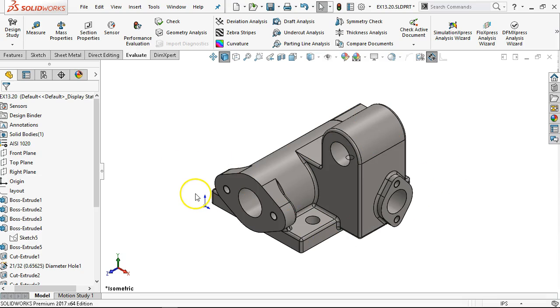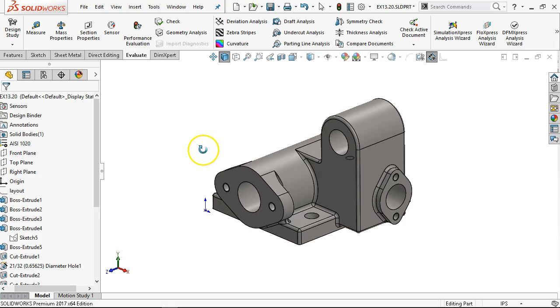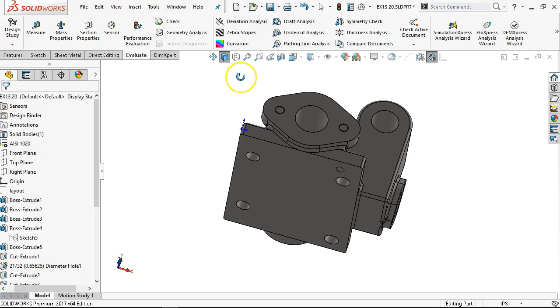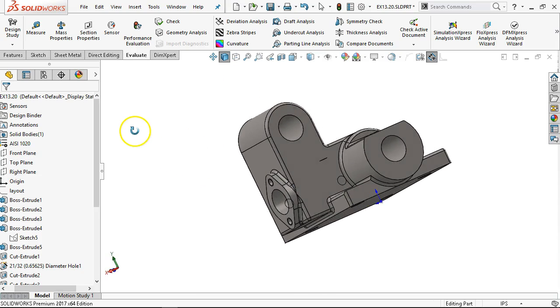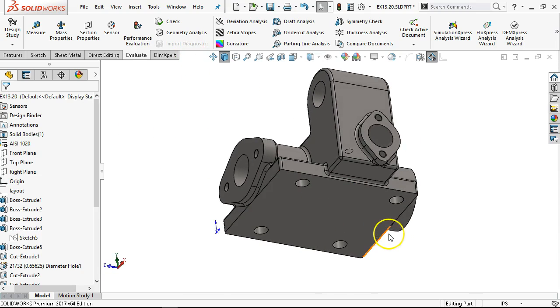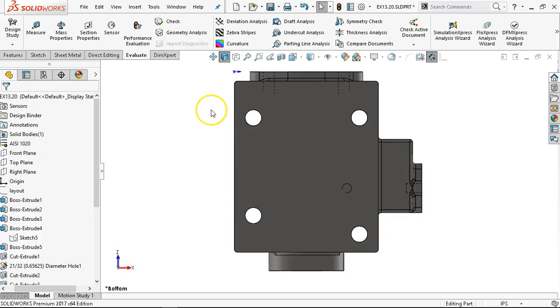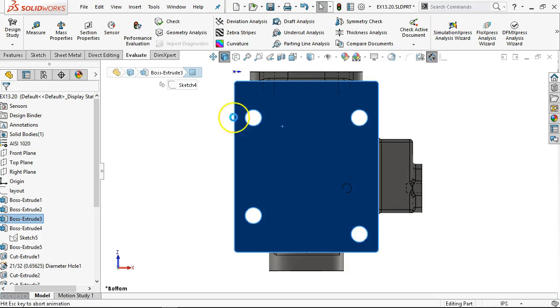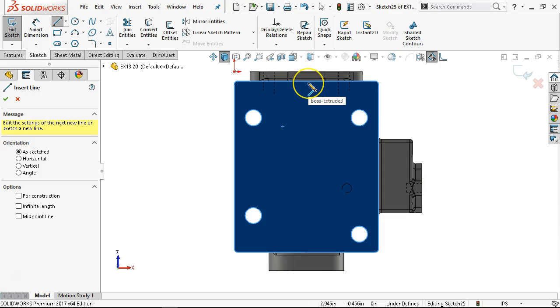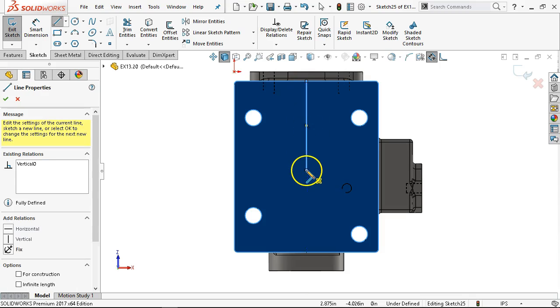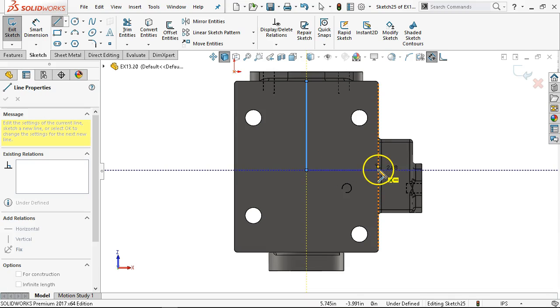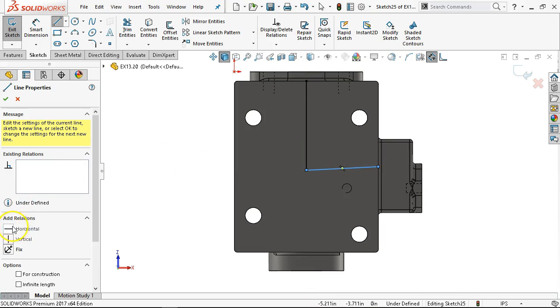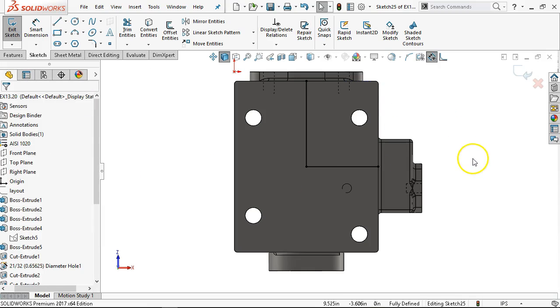All right, so if I wanted to change this position, now let's find something a little more convenient than the radius edge, since I'm going to have to build it out anyway. I'm going to open up a sketch, and we'll go from midpoint to midpoint, and that can be horizontal.